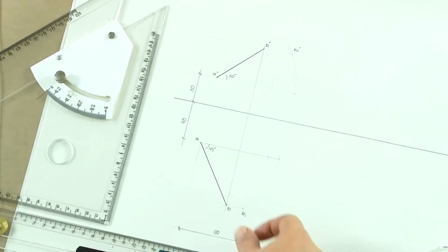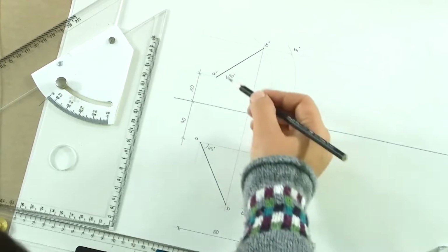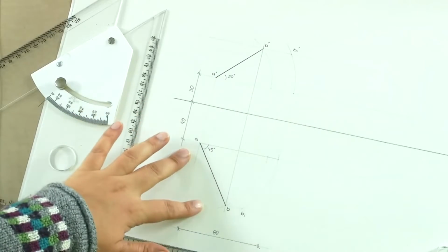Sometimes you would find that these lines are not necessary, but the direct use of this one is when you calculate the shadow angles when you are studying climatology. In that case, the angles which we are seeing here, inclined to both the planes, are the angles that the light rays, the sun rays, are making with the horizontal as well as vertical. And in that case, how you design your shading devices and how the shadows will be calculated will be determined based upon how you arrive at the projections of doubly inclined lines here. It is exactly the similar principle.